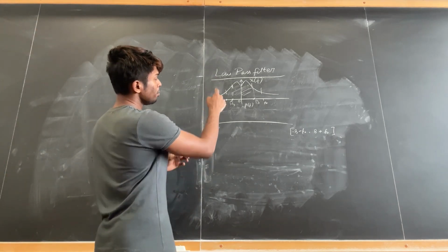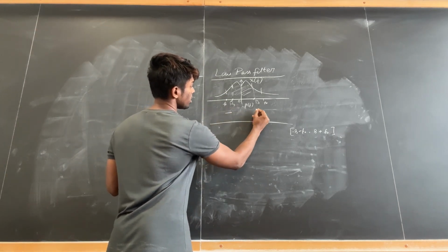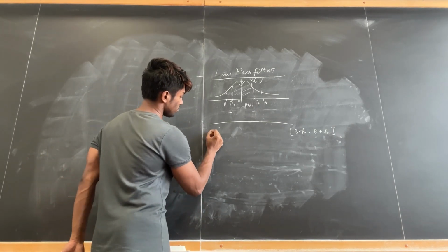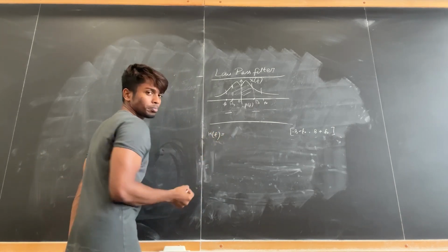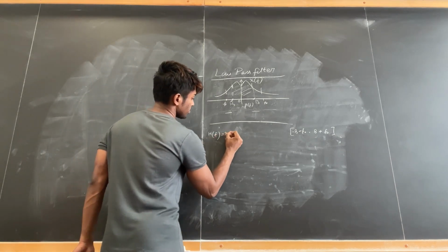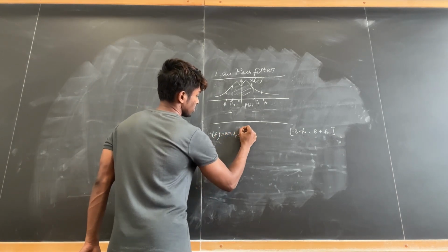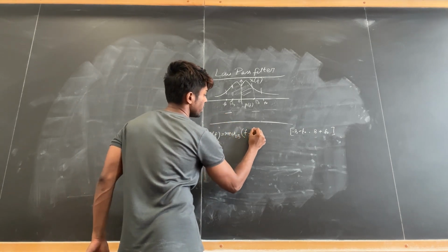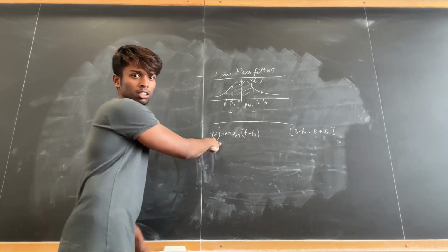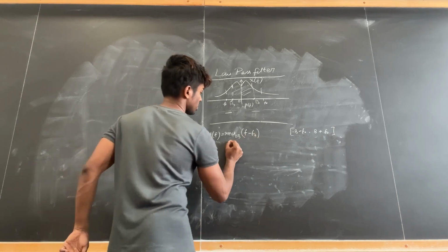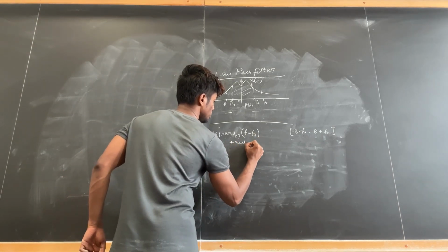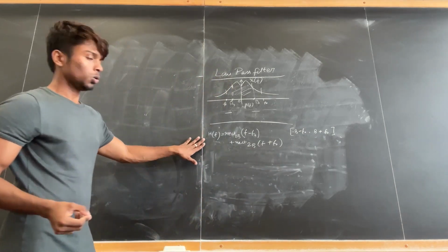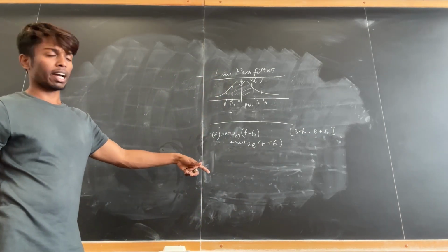So the frequency response should be some rectangular function specific to those bands of frequencies. We can define that H(f) is equal to rect(f minus f0 over 2B), where f minus f0 is a particular frequency specific there, plus rect(f plus f0 over 2B). So we only allow a certain band of frequencies, and that's why it's a band pass filter.